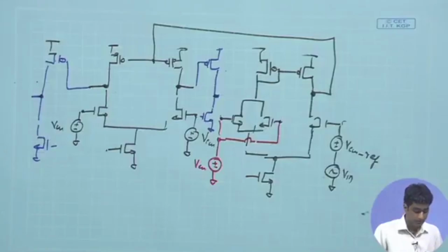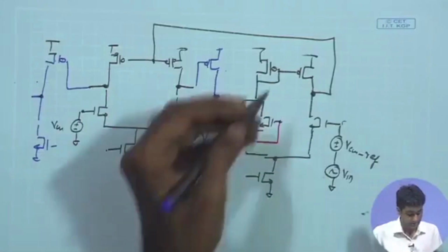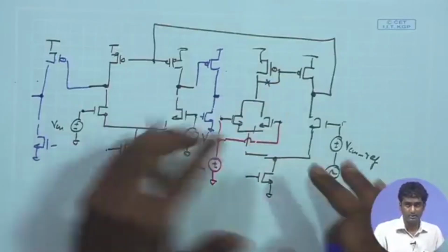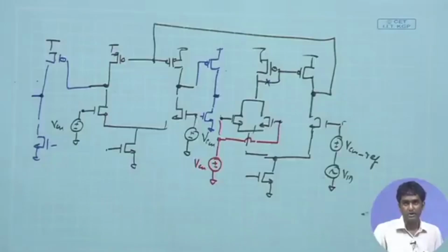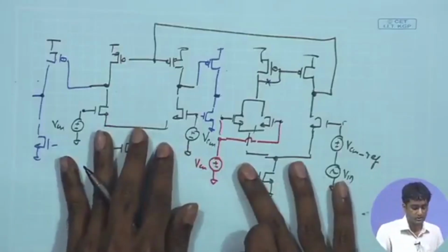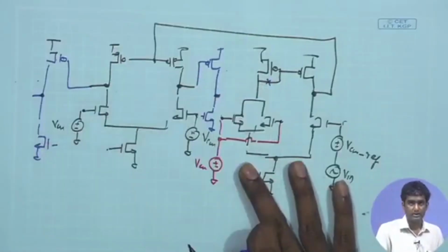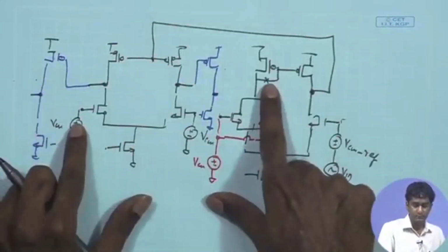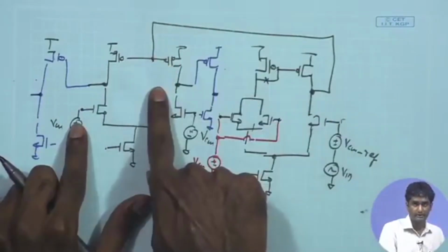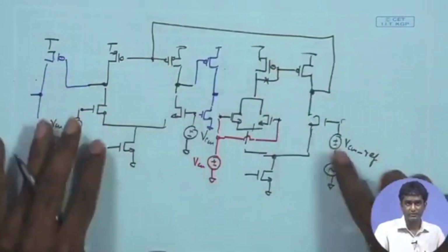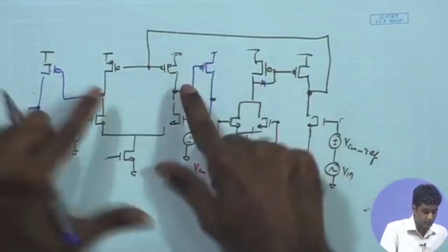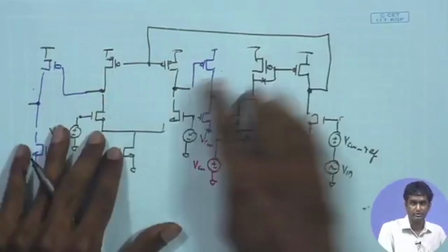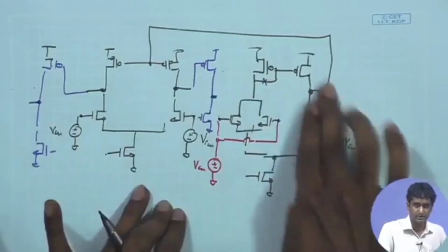The other thing that you also need to make sure is that you are checking the polarity of this one. Some of you have pointed out that when you connected the 2 stages in the loop, this particular scheme was not working, and that is because you have probably not changed the polarity, because for the single stage, this is the correct polarity because it is giving us overall negative feedback. So, you can trace it back and check whenever you have doubt. Assume that you are just having the single stage. In that case, you are just trying to trace and figure out that yes, this connectivity was correct.